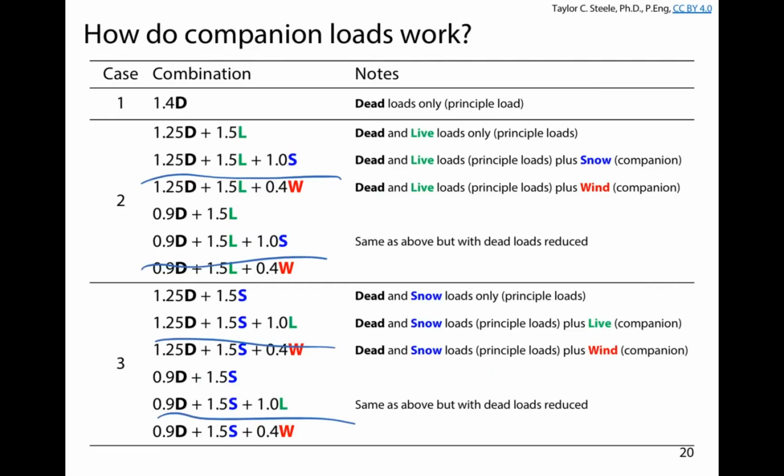That leaves me primarily with different dead load and live load and snow load combinations. Now we've got a bunch of different ones to consider. We're obviously not going to ignore the snow or live because that's going to add. So we do want to add everything together. We're certainly not going to reduce the dead load. That's not adding to the compression on our column. Ultimately, this comes down to, are we going to put the bigger factor on the snow load force, or are we going to put the bigger factor on the live load force?